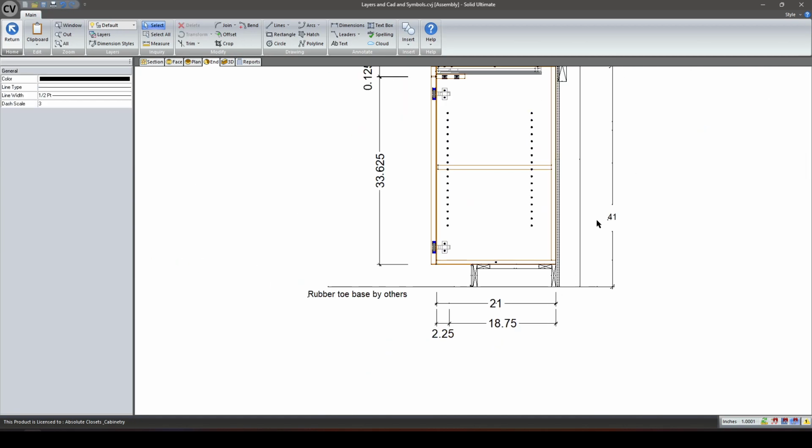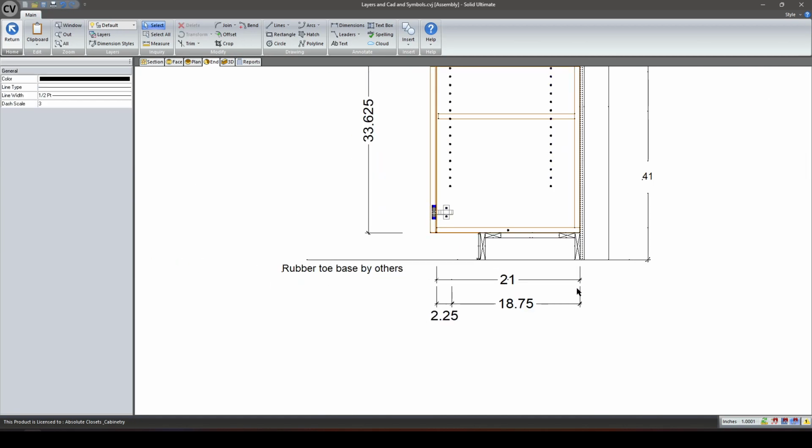this one could be automated in the same way that I've shown this. You just have another set of CAD lines that come out with a little text note here with an equation to always call out the cabinet's depth minus the cabinet's toe recess, which is easy enough to get to. And now you've got one less thing that you have to work with.